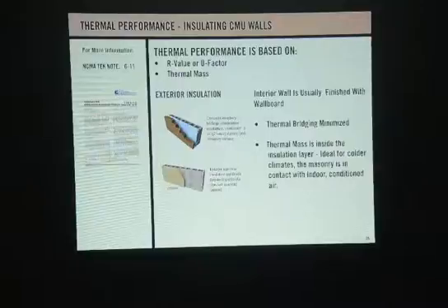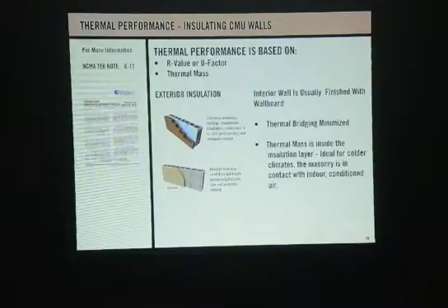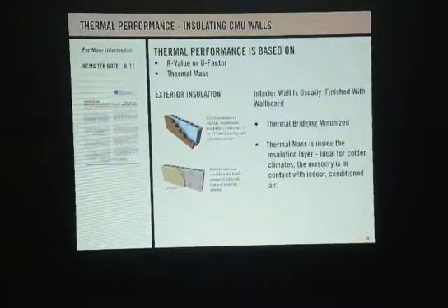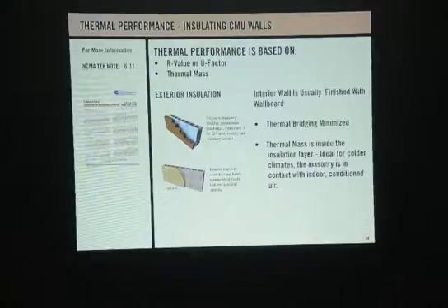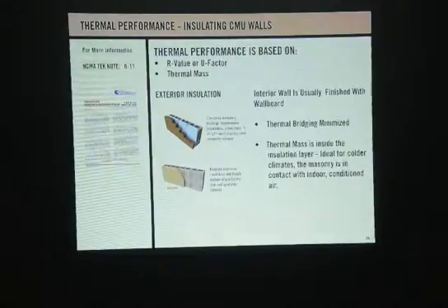Drywall is an organic food source, okay, so that feeds it. So sun, light, and ventilation. The last one, the fourth one after organic, is moisture. If we can shut off one of those environmental elements, we don't have a problem with mold and mildew. But if all four of them are present, look out, okay? Just thought I'd let you know what I learned over the years.